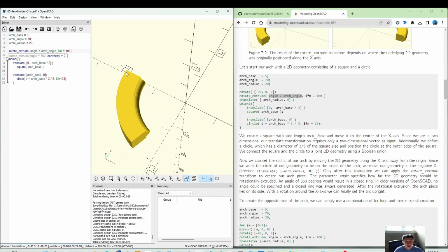The rotate takes the original 2D shape and rotates it based on the X axis, makes it upright, and then rotates based on the Z. The reason we move this from the origin to the negative X is to ensure we are doing this rotate with a certain angle.